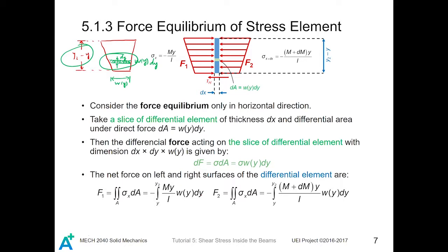Since at the upper end of this stress element there is no force, there must be a horizontal shear force that holds this piece in equilibrium. So in the horizontal direction, there is a shear force VH.